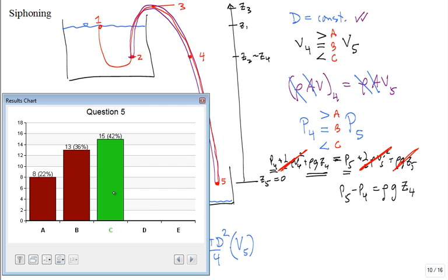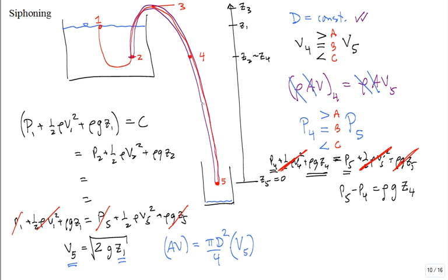So that's correct. True? Did that make sense? Okay. Let me ask you this question. What does it look like the pressure at 5 is? I already mentioned it at the beginning. Is it below atmospheric pressure, above atmospheric pressure, or near atmospheric? It's right at atmospheric pressure. And we just concluded that the pressure at 4 is below the pressure at 5. Describe the pressure at 4. It's a state of vacuum.